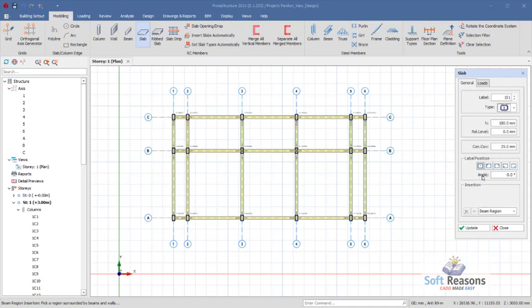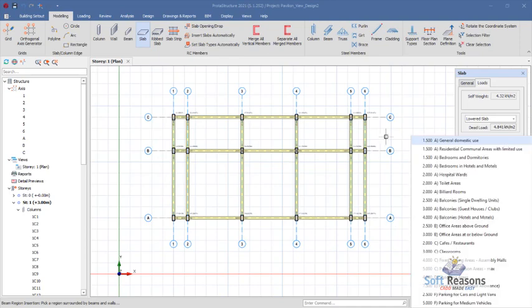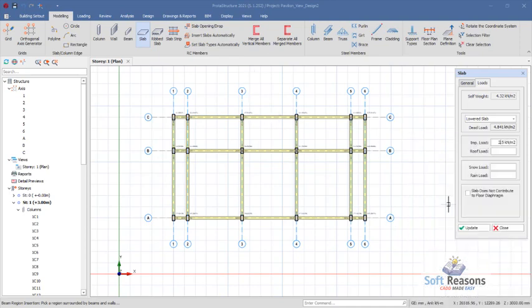For slab level positions, we use this center point, go to the load options, and then we will consider lower slabs options. This one, you select that to apply the additional dead load on that. So this is a commercial structure, so we'll be considering 2.5 kilonewton per square meter for the imposed load, just like this. Okay, so at this point we start to place the RC slab just like this.